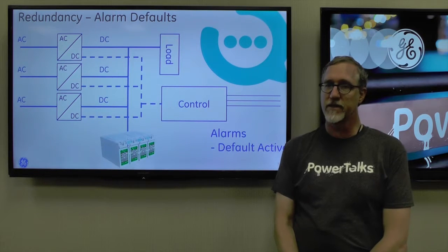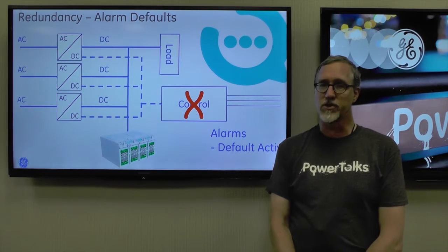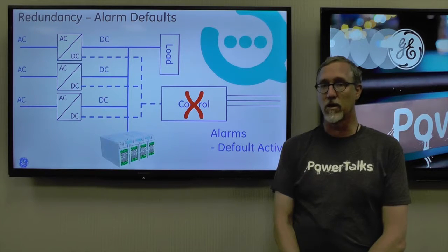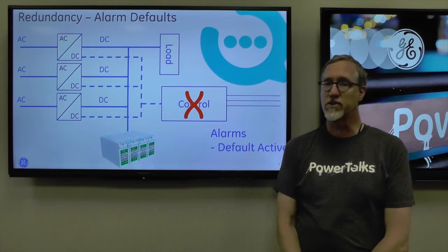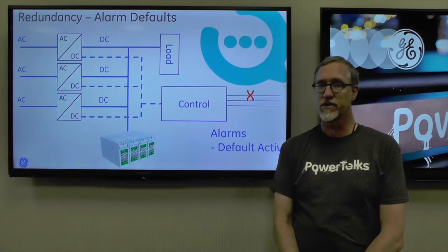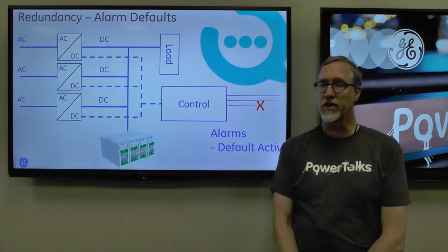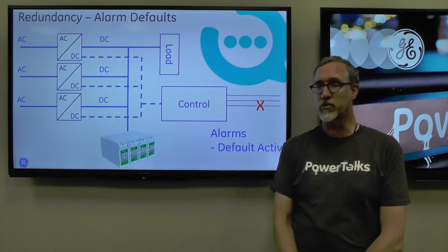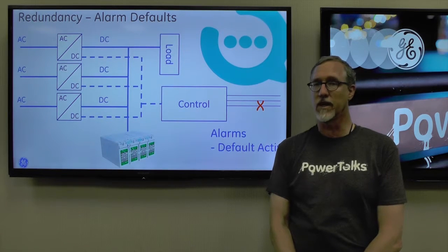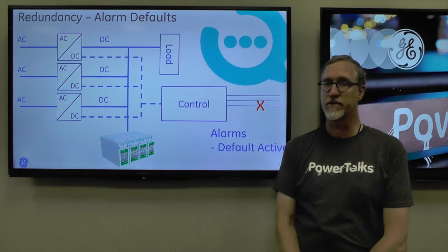In this way, disconnection of the controller will generate an alert or alarm state. Even if the problem is cut or damaged wires, the remote monitoring location is alerted of a problem. Similarly, a controller alarm can be generated by the controller failing to hold its relay closed for normal operation.